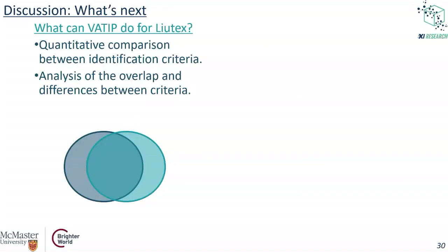What VTIP will enable is that because it's going to exactly extract all the vortices in the flow field, it allows you to do very quantitative comparison between different vortex identification methods, including different second-generation methods as well as VTIP. So when you have different vortex criteria, you can find the vortices identified by, let's say, Q or lambda, and you can find the vortices identified by VTIP, and you can look at which vortices are common between the two sets, which are different between the two of them.